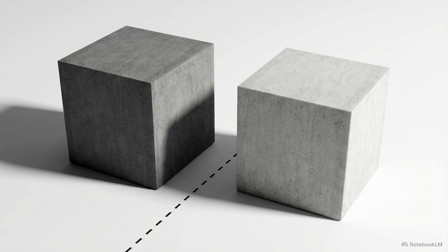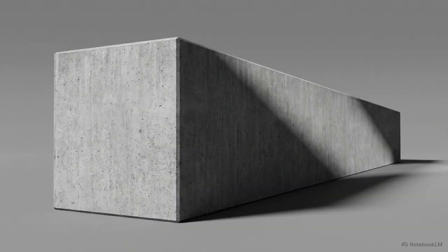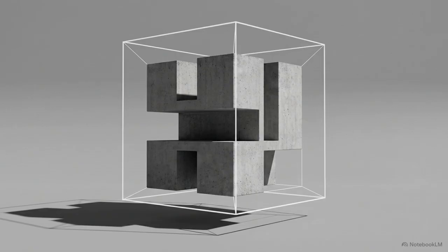The second family encompasses additive and transformative operations, the process of attaching material and altering the relationships between volumes. When project requirements dictate a larger footprint, these actions expand a building's square footage to meet complex programmatic demands. On this primary gray volume, we extrude by pulling one face outward to extend its length. We then offset, creating a secondary boundary line that expands proportionally outward from the original shape.